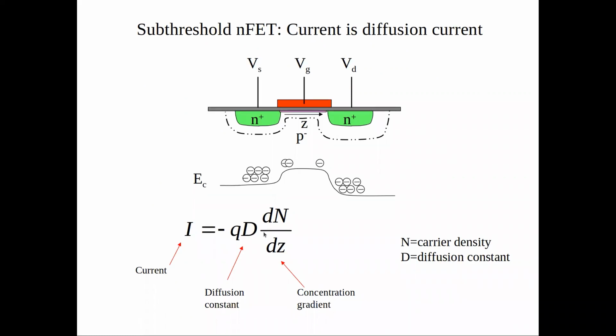The depletion region here is something we have just by construction. It's not like we can control it. It's there because we're putting together P and N material. The dashed line, or the region between the active area and the dashed line, is only showing the depletion part of the P material.